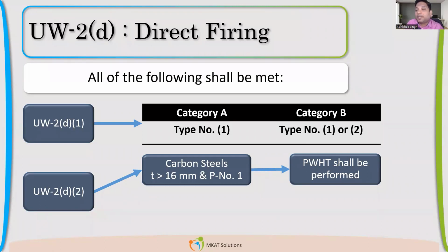Like P number 1 material, if none of the critical requirements apply, right? Himanshu has already posted 38. Whether it is 38, it can't be 32. Yes, it's absolutely right. 32 if no preheat. If we are doing preheating, then we can extend it up to 38. Beyond that, it becomes mandatory.